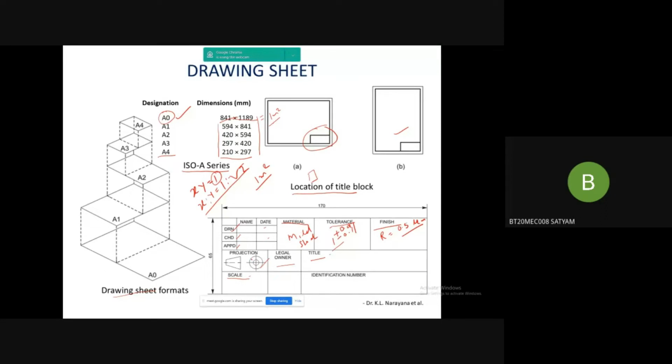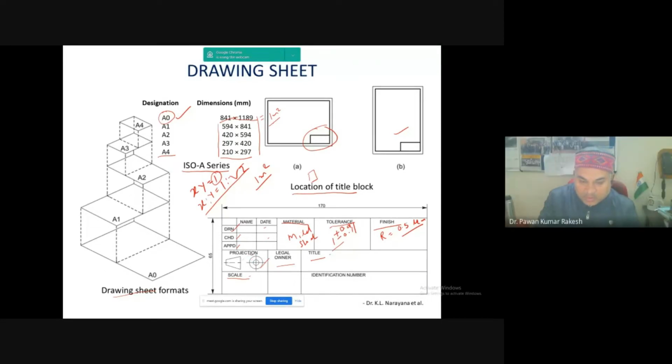Yeah, this is the symbol of first angle. This is the first angle projection. So in India, according to the Bureau of Indian Standards, generally we follow the first angle symbol, right? So this first angle projection we generally use. This is the first angle symbol. This is the first view of the cone, right? So you can see this from this side, and you can draw the projection on the vertical plane. So first arrow, this circle and second circle. So this is the first angle projection.